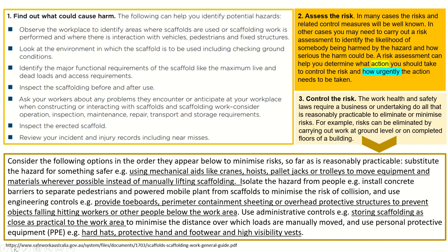Yeah, so what is the most important task in the risk management cycle is the identification of hazards. That means you need to know what kind of potential hazard are relevant to the temporary structure. And then the last stage is you need to know different tasks and tools and equipment available or possible to be considered for controlling the risk.